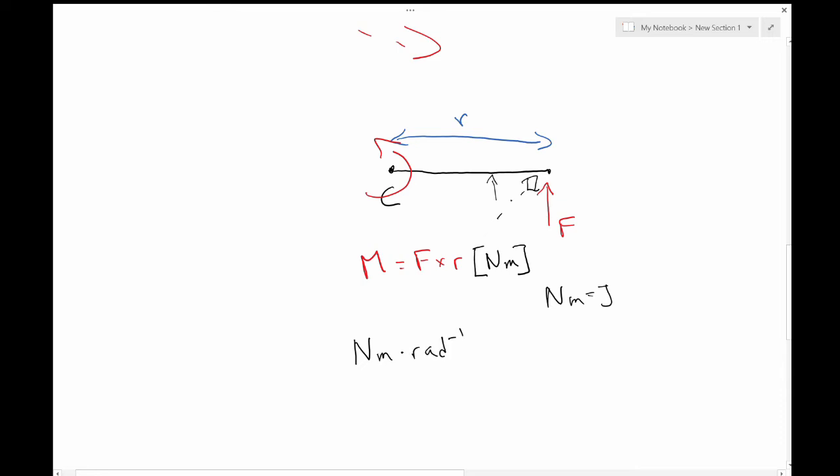So that means that in the same way that force times distance is going to result in a certain amount of energy that it takes to push something, a moment times the amount that you rotate it, the rotational force times the amount that you have to rotate, is going to give you energy once you multiply out this radian term. But because radians are technically dimensionless, that doesn't make it into our actual units for the moment.